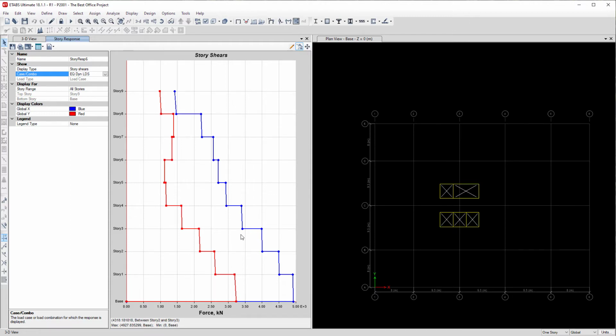And because of this distribution of the shear forces on the building, that actually reduces your moment, because that brings your action force, instead of being up here, for example, you can bring it down here closer to the ground. So that reduces your overturning moment. So we end up with 90 something thousand instead of 145. Now that is a big difference in the analysis, and it actually reflects how the building is going to behave.